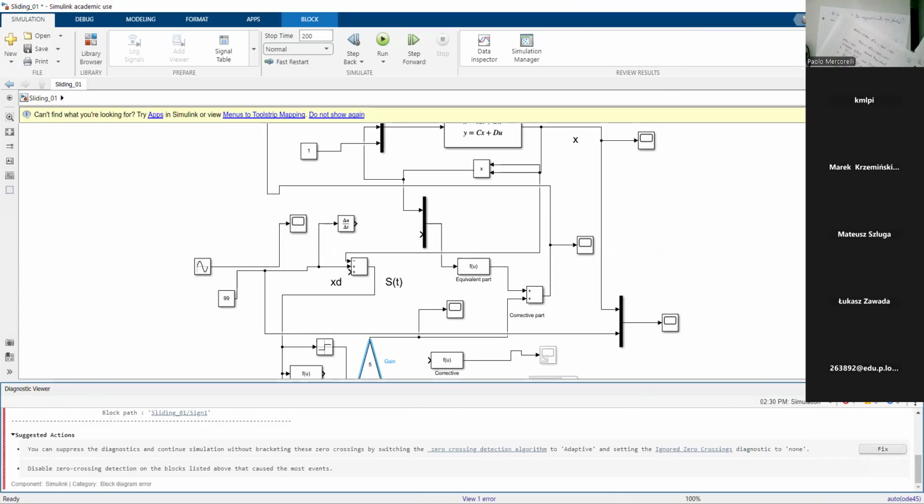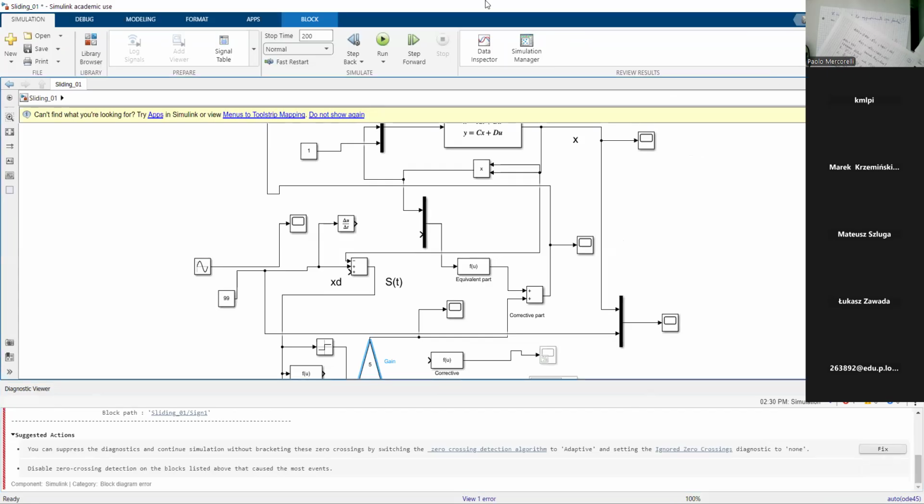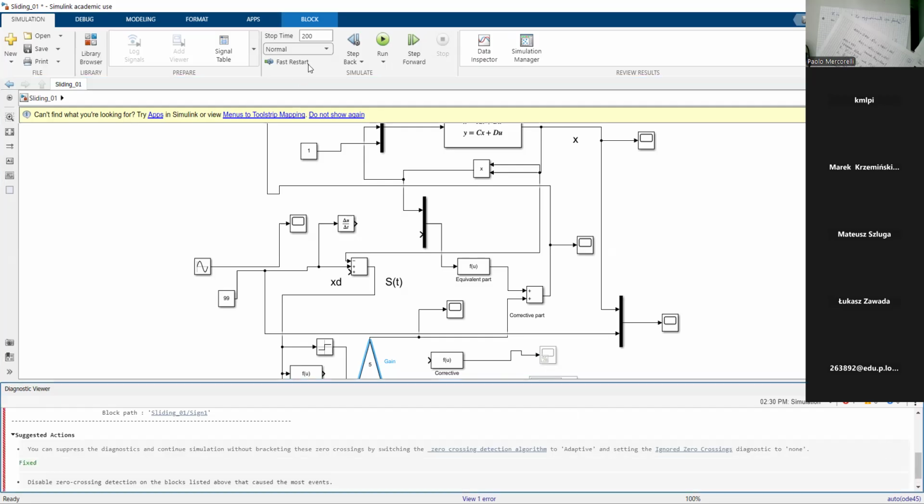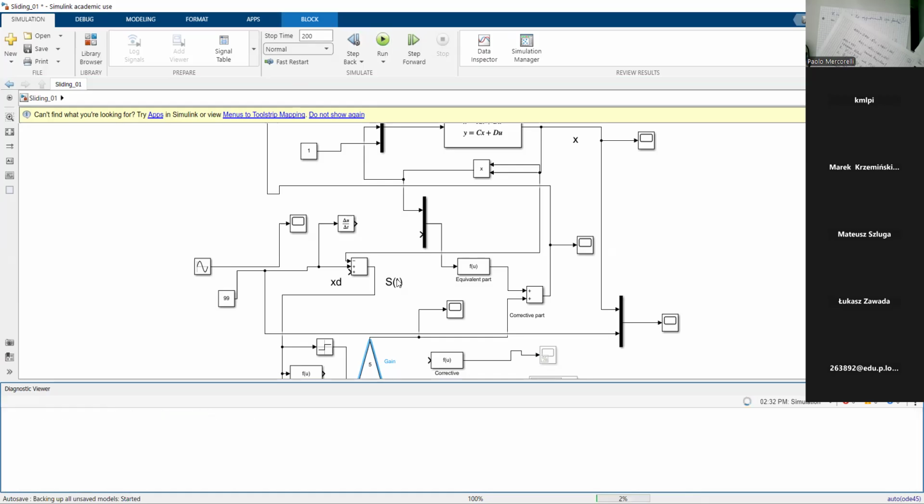Otherwise, practically, if I fix, the system approximates this sgn internally again, because in a very small interval or region where you have to switch theoretically around zero, if I oscillate around zero we switch between 1 and minus 1 and the system could have problems in this oscillation. If I fix it, it generates a tolerance region.